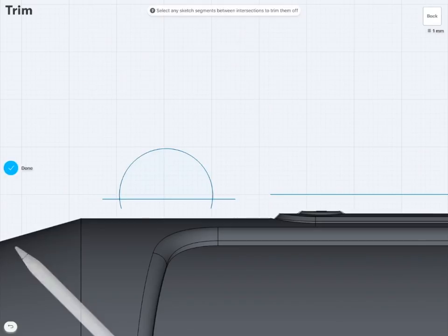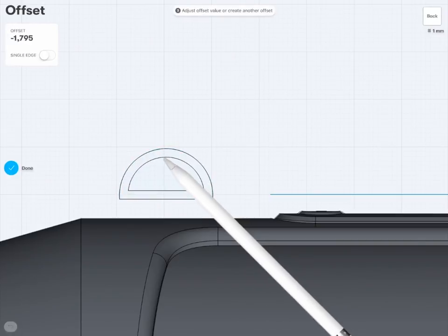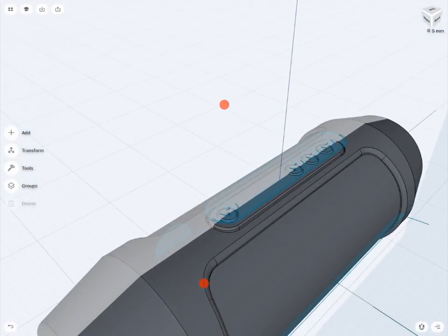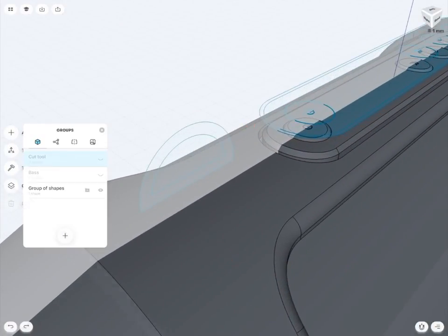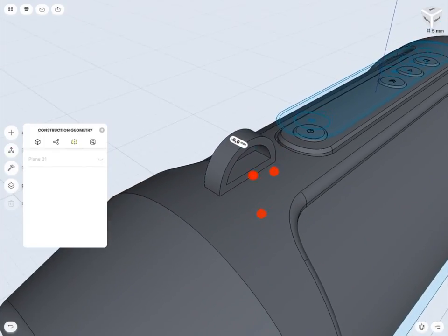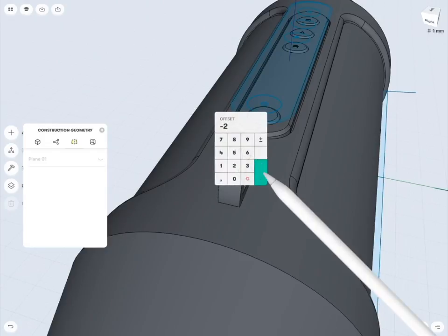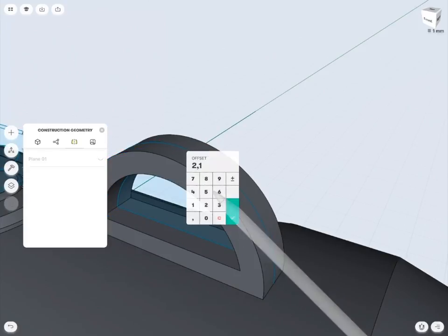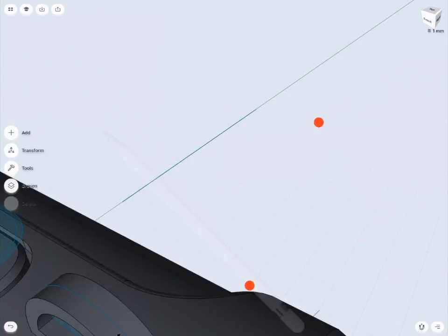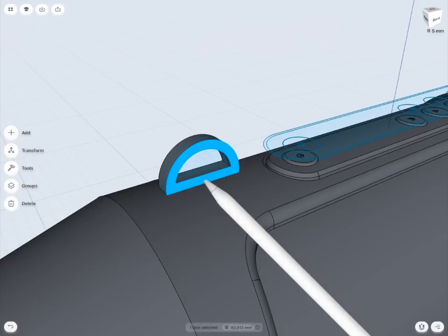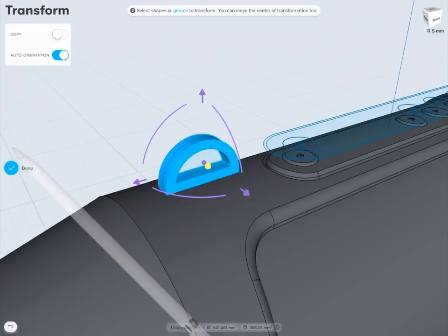Basically, there is nothing new about what I'm doing right now. It has already been done previously. This process is more conceptual, and this is why I don't need to be very precise. I prefer to sketch, extrude, and then transform to match the initial idea without extra precision. I'm creating this mounting wrap, and I'm also transforming it the way I want. You can still transform it later if you want, but I think it's quite big at the moment. That's why I'll scale it according to the center point of the edge.